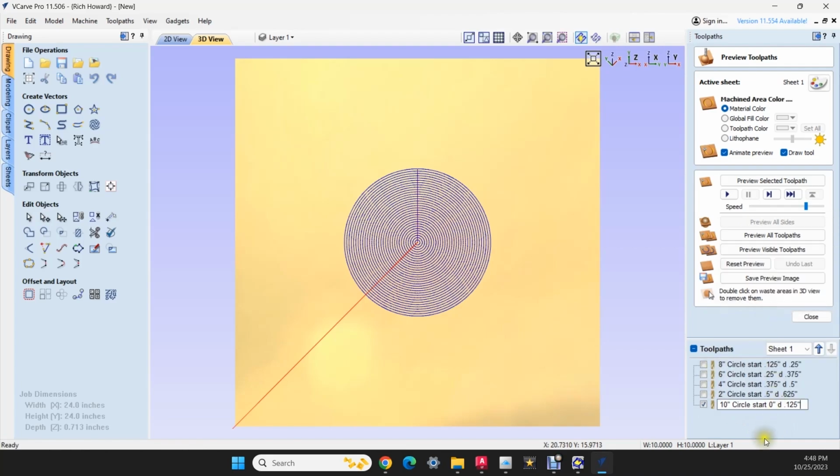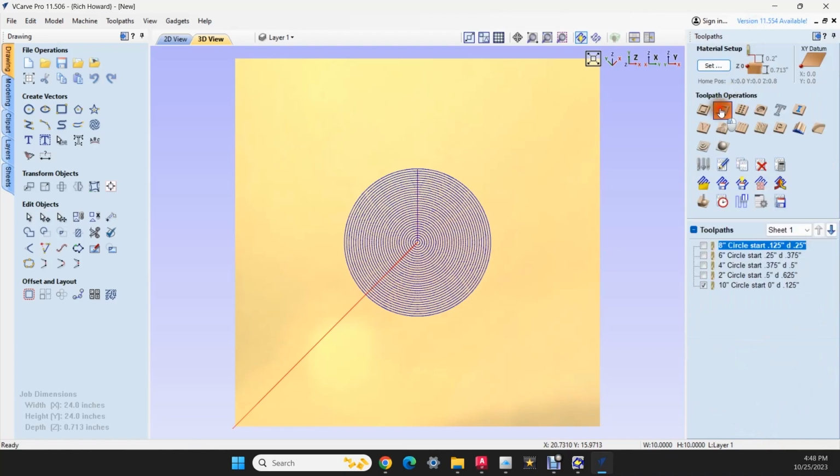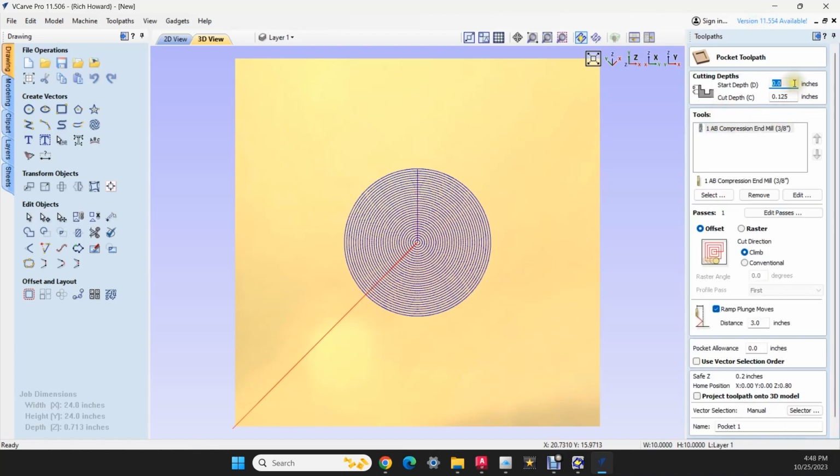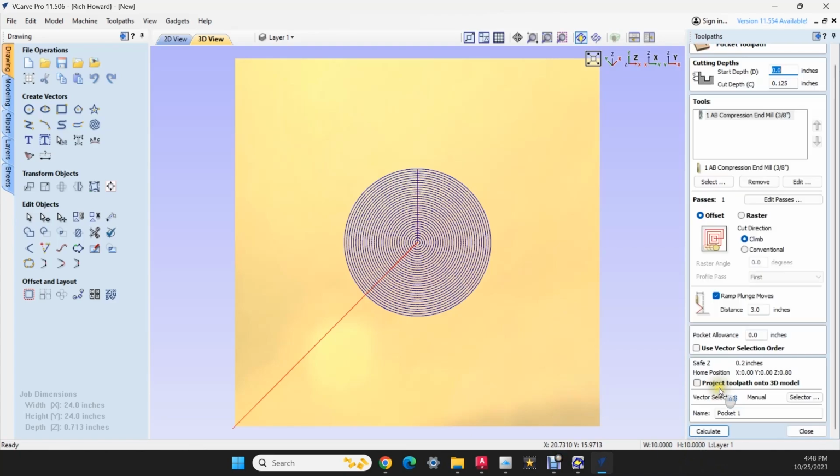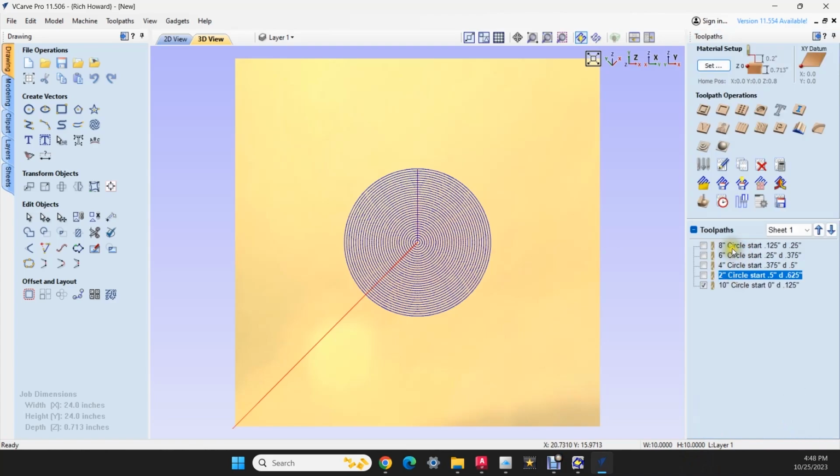Rename. Right. Now here's the mistake, and it caught us down here. What I'm actually asking it to do on the 8-inch diameter circle is start at 1/2 inch, and then my cut depth was 5/8, and that's where it's getting 1 1/8. What has to happen is the cut depth needs to stay always 1/8 on all these toolpaths. So let's fix it.